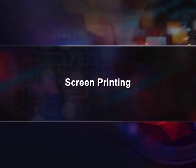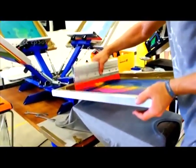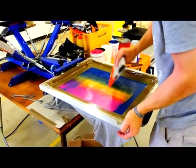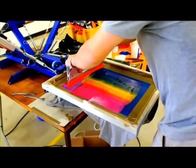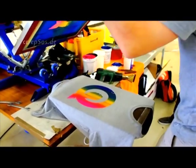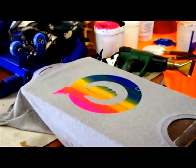Screen printing. Screen printing is a printing technique whereby a mesh is used to transfer ink onto a substrate, except in areas made impermeable to the ink by a blocking stencil. A blade or squeegee is moved across the screen to fill the open mesh apertures with ink, and a reverse stroke then causes the screen to touch the substrate momentarily along a line of contact.